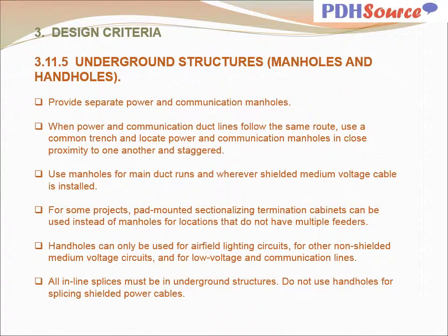For some projects, pad-mounted sectionalizing termination cabinets can be used instead of manholes for locations that do not have multiple feeders. Handholds can only be used for airfield lighting circuits, for other non-shielded medium voltage circuits, and for low voltage and communication lines. All inline splices must be in underground structures. Do not use handholds for splicing shielded power cables.